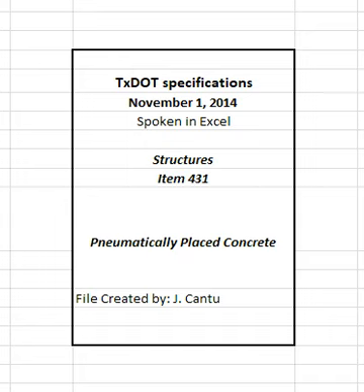3.7 Curing. Cure encasements with water for 4 days. Cure repairs and structural construction using either a piece of wet burlap taped over the repaired area with a covering of 4 mil minimum plastic sheet also taped in place or membrane curing as approved. Overlap the burlap with the plastic sheet and continuously tape the edges with a tape at least 3 inches wide, air duct tape or better, to completely enclose the mat and hold in moisture. Cure in this manner for 4 days.